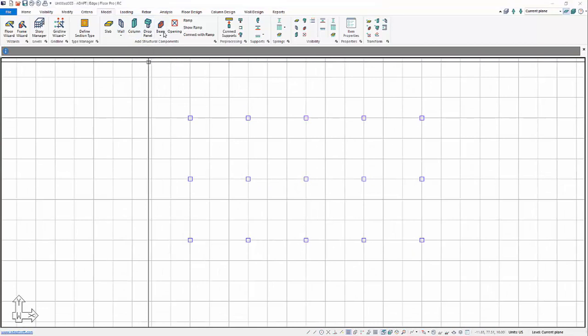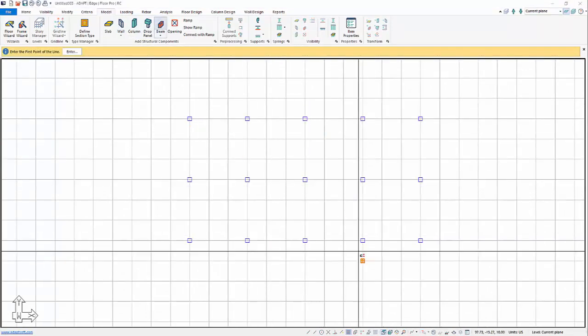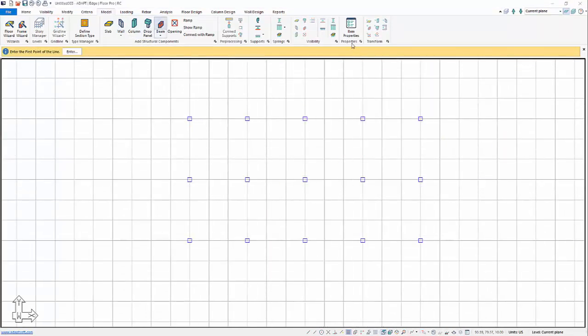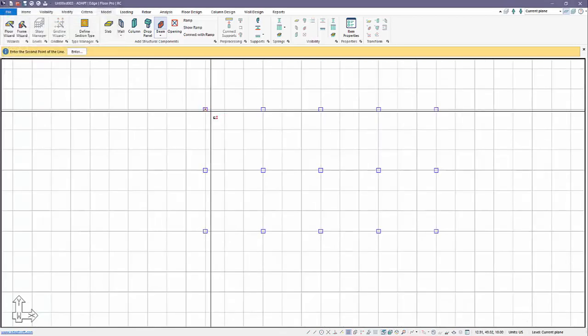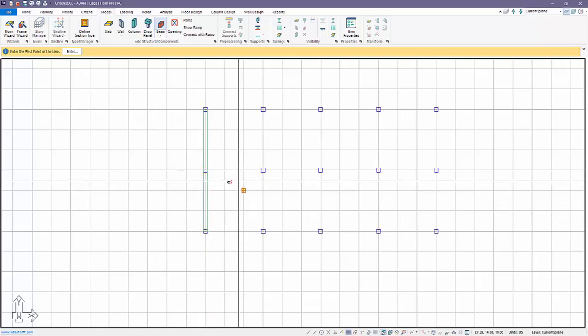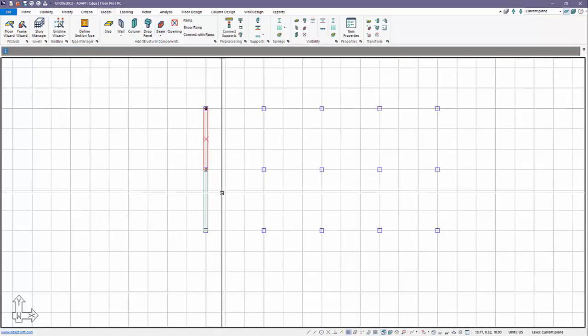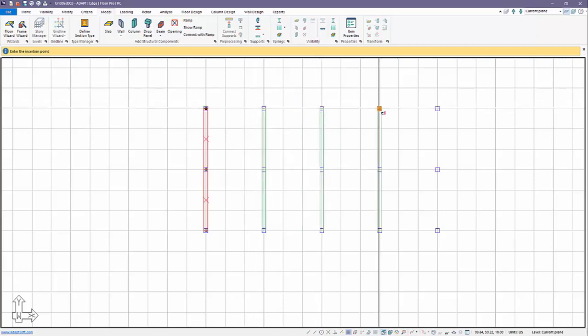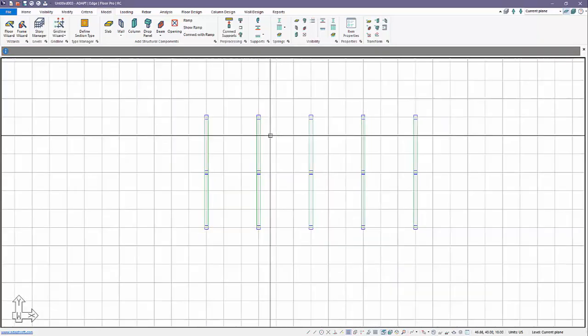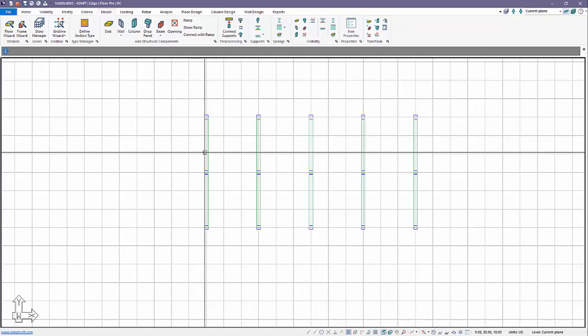And then we're going to model some beams. So these might be post-tensioned or RC beams with a one-way slab, for example. We'll make the beams 24 by 20 by 21 inch deep beams. And I'll select those and copy those to the columns. Okay, and then we're going to model a slab on the perimeter.